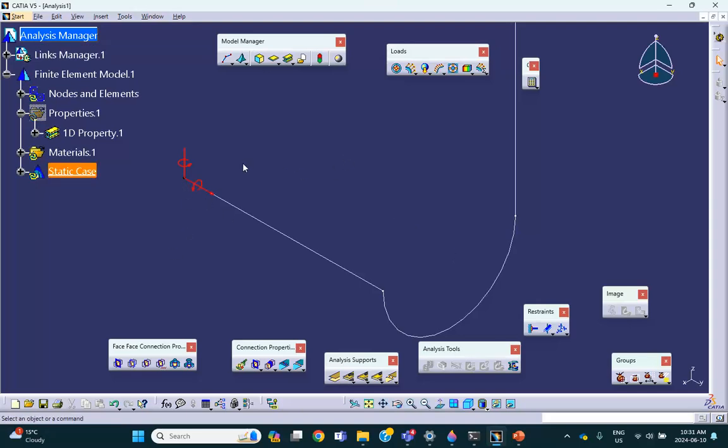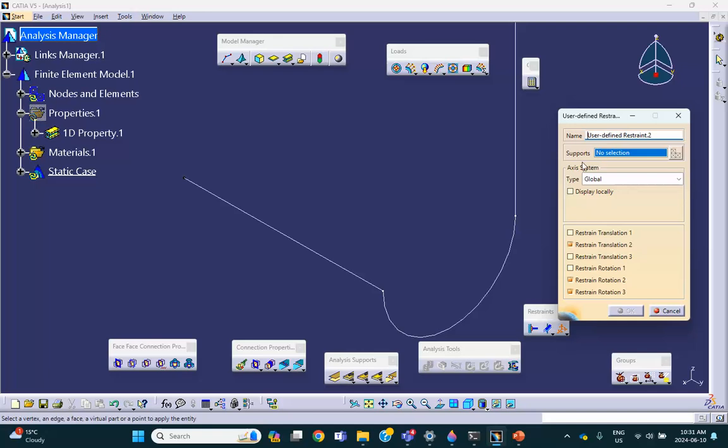And then I want to push this point down, right? So I'm going to hide that for a second. Another one. Push down. So I'm going to say push down. Push down means first you make it 0. That means 0 in the direction Z of this point. Okay.